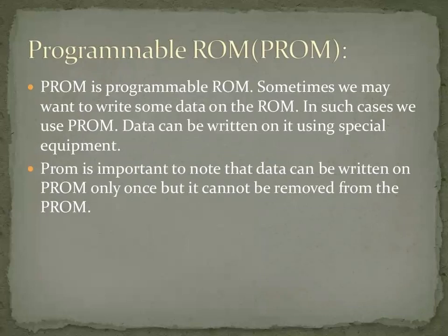Programmable ROM, PROM. So what is PROM? PROM is programmable ROM. Sometimes we may want to write some data on the ROM. In such cases, we use PROM. Data can be written on it using special equipment. It is important to note that data can be written on PROM only once, and it cannot be removed from the PROM. It is stored permanently and cannot be removed at any cost.